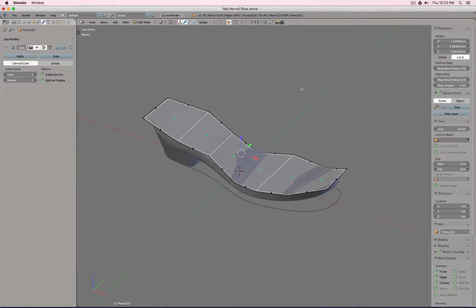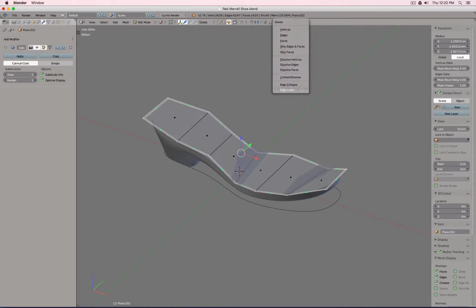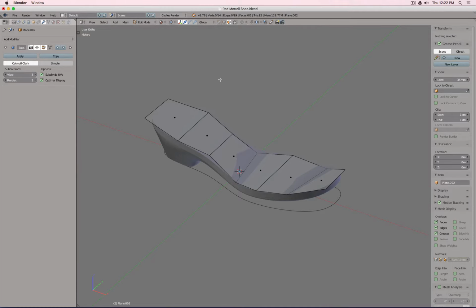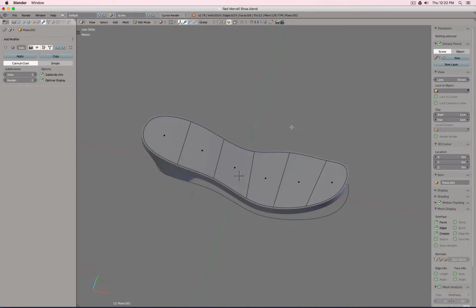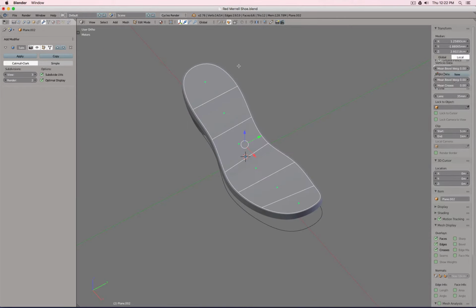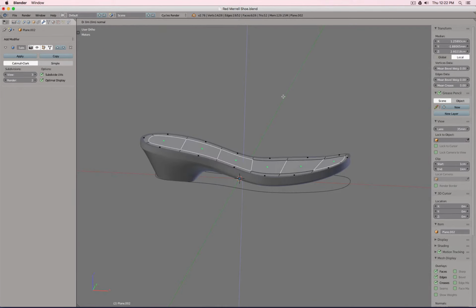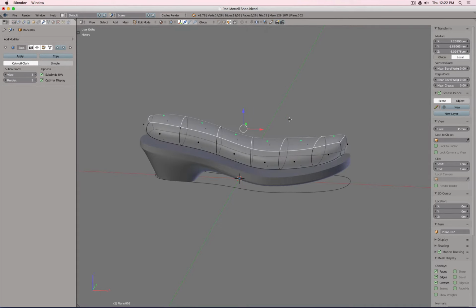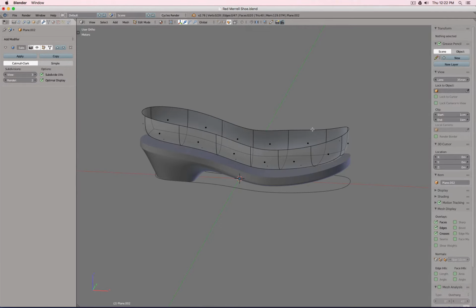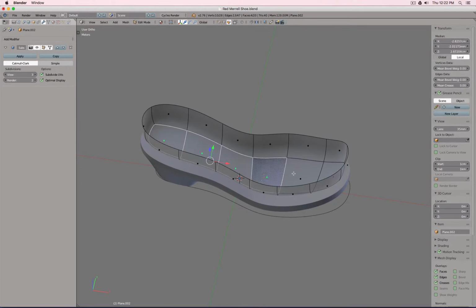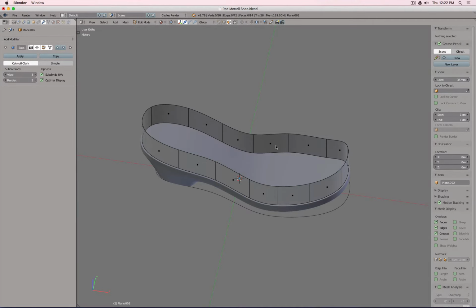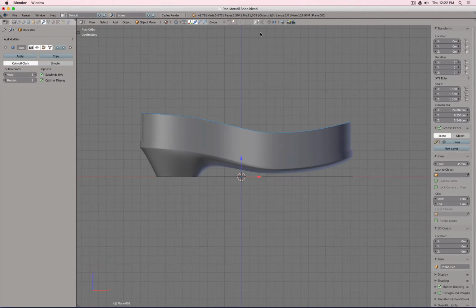Okay. Control I to select the rest, delete the faces. Let's take a look, and there you see we have a nice offset. Perfect. So all this we can select. E, Escape, Z, move it up, delete these faces, and also here we delete these faces. There.